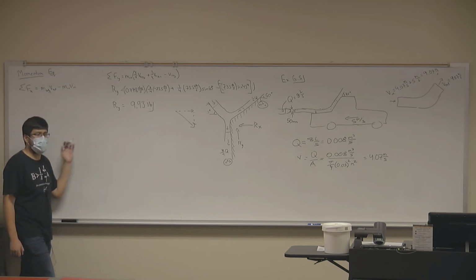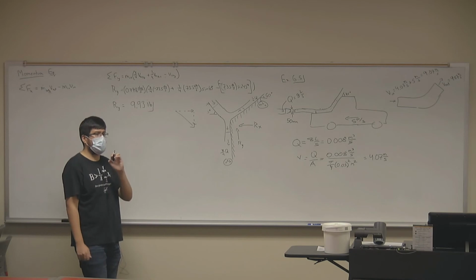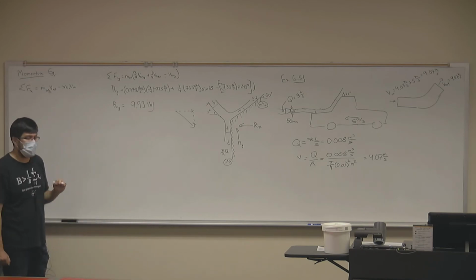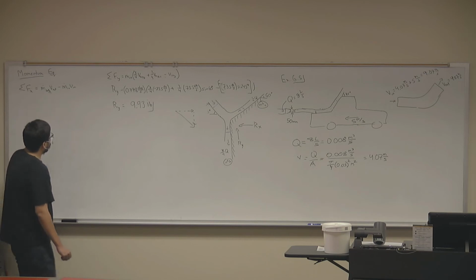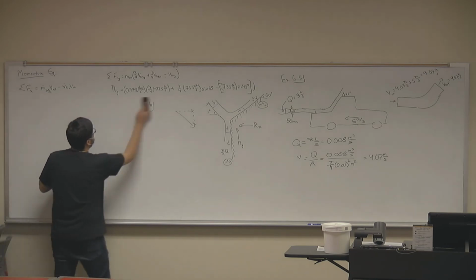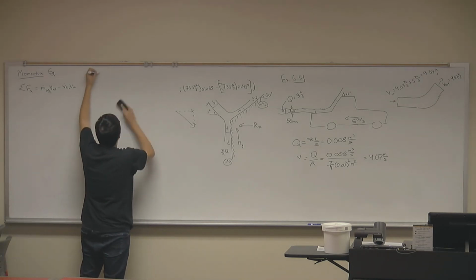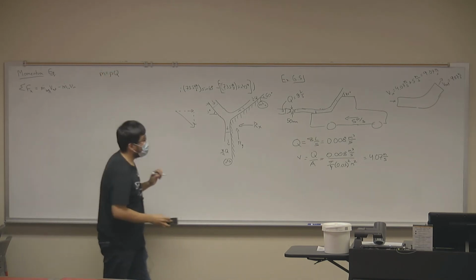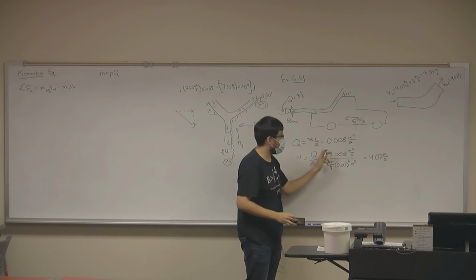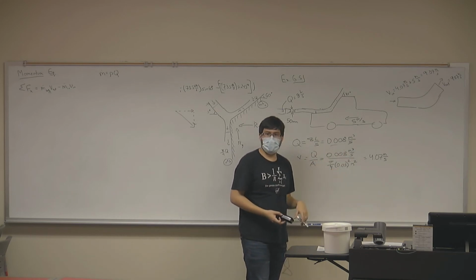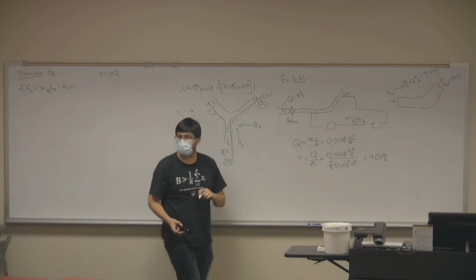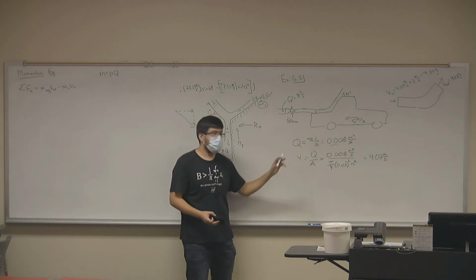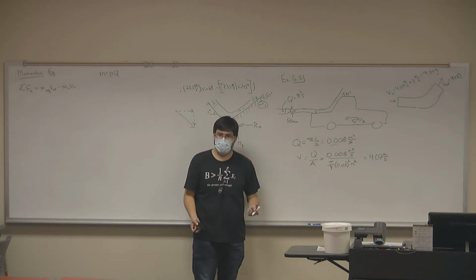Technically, we could factor out mass flux, but before we do, I need you to understand what this mass flux represents. We know that mass flux is equal to density times flow rate. So is the mass flux in this control volume equal to density times 0.008? Why not? It's the relative velocity. Exactly, right? So let's not make the mistake of thinking, well, we have mass flux.